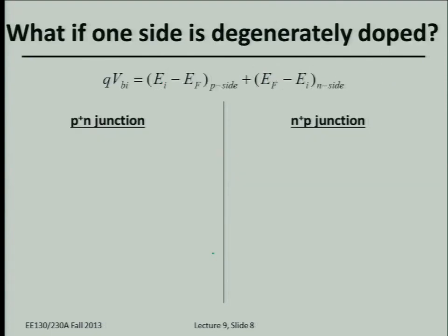Now, you're going to get tired of seeing the transistor by the time we get to work on the transistor. Usually in a transistor, the source and drain regions are very heavily doped, usually degenerately doped. For a p-channel transistor, you have heavily doped p-type regions with a lightly doped n-type body. In any case, it's quite common in an integrated circuit to see one side doped much more heavily than the other, and one side could be doped so heavily that it's degenerately doped.